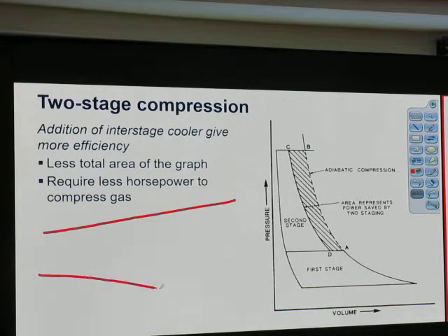In a slow, gradual expansion, we have gas coming in, and the velocity far away from the inlet is less than the velocity at the inlet. The velocity goes down because it's expanding. When velocity goes down, from Bernoulli's law, instead of a pressure drop, we gain pressure.